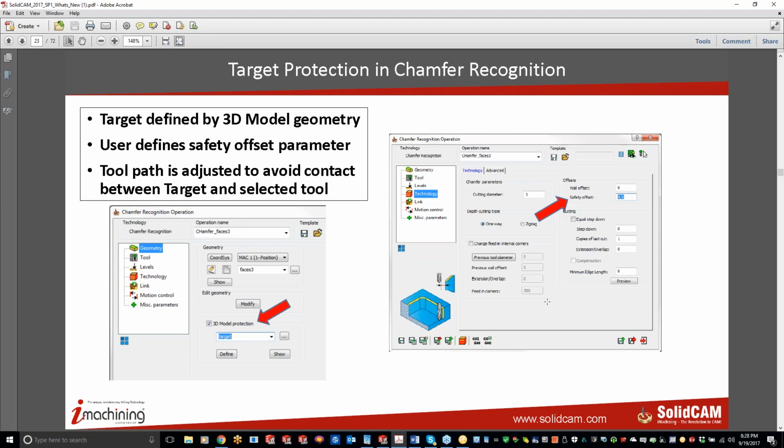So if you guys are getting into a tight corner, instead of the tool coming right up next to it, you can actually type in a distance in there now. So that maybe your tool is just a hair bigger than what you said, and it's not rubbing on the edge over on the right side or left side. So yeah, let me drag down my questions here.